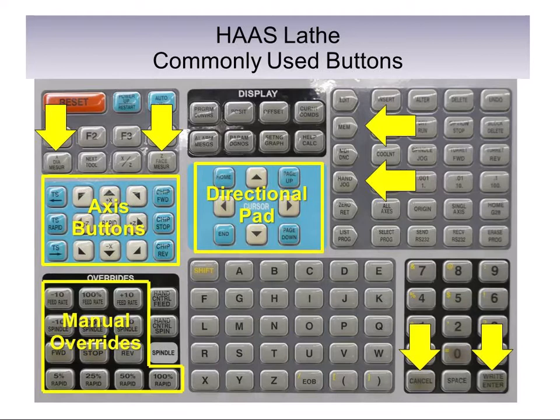Hand jog, the speed that you're going to hand jog. Zero return, all axes, origin, single axis, or home G28. Home G28, unless you specify which axis, will take all axes home, so you want to make sure that you got clearance for that. And then also list programs. So you can select your programs. You can use your file format to help you figure out, do I want to take a program from memory, or from the USB, or from the hard drive.